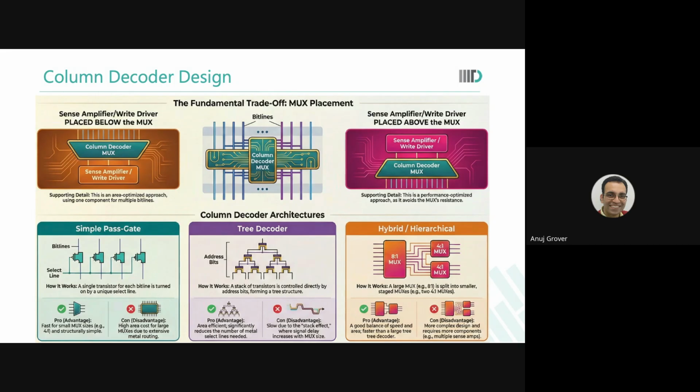We say that the bit line should be precharged to almost equal values, close to the desired precharge level, before the read operation starts, before the word line comes. So we have essentially just now also put a trade-off between almost equal bit lines as a reset time or cycle time, and we have said that excess time would be after that.